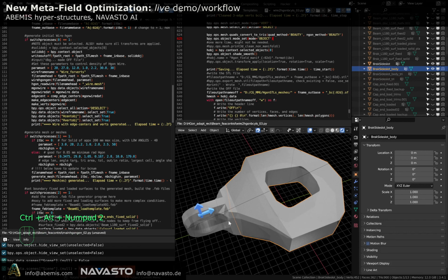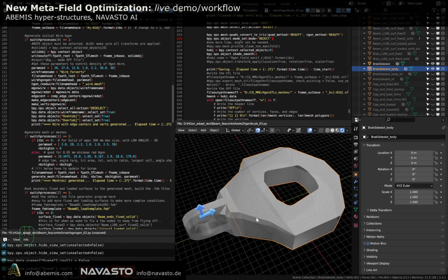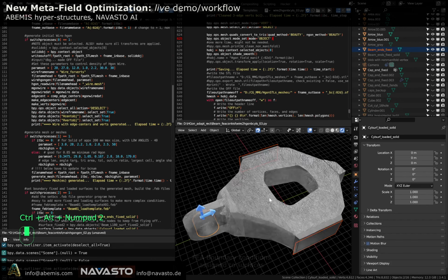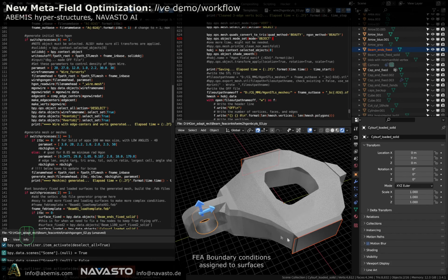We have to keep this shaft connector end piece here. So I've just used a simple Boolean to segment that part from the body. That segment gets automatically reattached later. First, we need to set some necessary boundary conditions. So you can see here we have two planes here for the fixed boundary conditions. This component's fixed at the ends where it connects to the rail underneath.